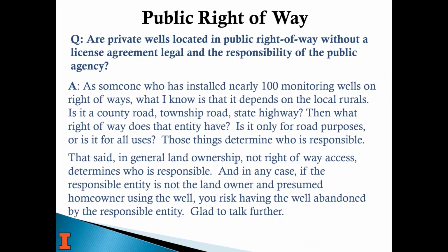Are private wells located in public right-of-way without a license agreement legal and the responsibility of the public agency? So yes, we put in a lot of monitoring wells, and I have to work with county, township, and state folks on the right-of-ways. There's two types. Sometimes they have a right-of-way that is for any purpose, and sometimes it's just for road purposes. When it's for any purpose, then, for instance, on a county road, the county can give me permission to drill a well, and that's it. Even though a farmer may own the land, because they actually own the land to the center of the road. It's just that there's an easement for the county, right?